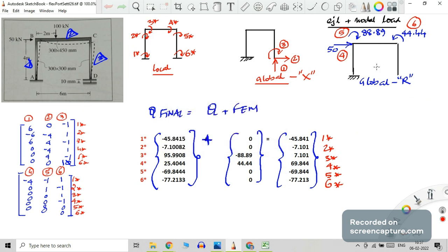So with that, we finish off the flexure case with the support settlement. So I have told you the principle. Always try to incorporate that support settlement into small x coordinate. That should be your target. Okay, in university exam problems, generally one or two settlements only will be asked, so that can be comfortably taken in small x. But if in a problem all the supports are settling, that also is possible.